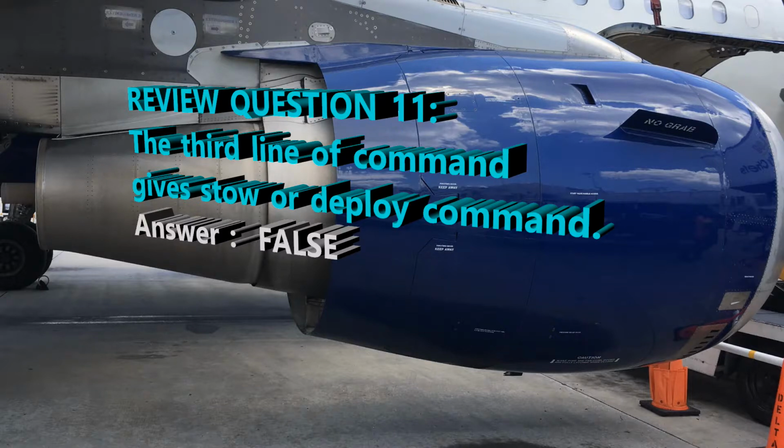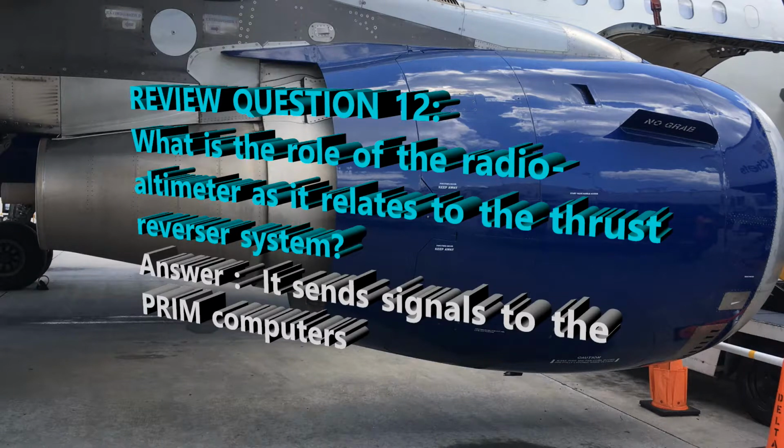All right, 12. What is the role of the radio altimeter as it relates to the thrust reverse system? Is it A, it sends signals to the engine interface function, or B, it sends signals to the primary computers? Okay, it's sending them to the primary computers. I know signals are going to both, but in this particular case, specifically, the signals are going to the primary computers.